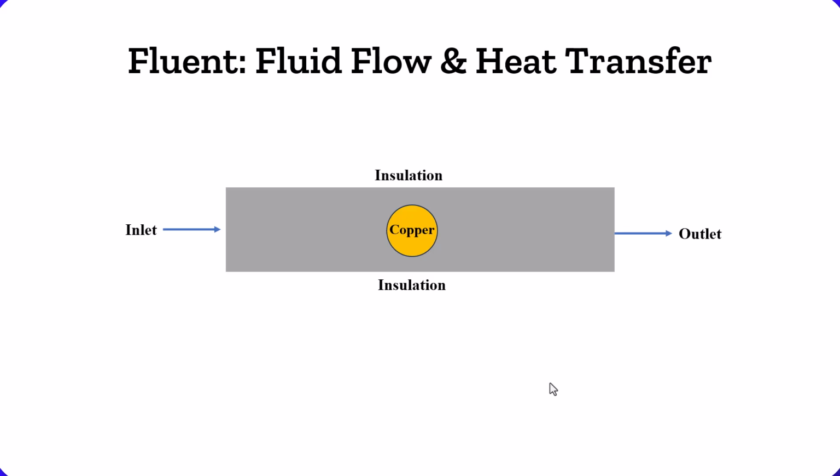In this video, I show you how to find velocity and temperature distribution inside a rectangle with a heat source. According to our model, we have a circle. This circle is our heat source. So we have airflow, the airflow inlet this section and out in this section. So we have two boundary conditions, the inlet boundary condition and also the outlet boundary condition for the outlet section.